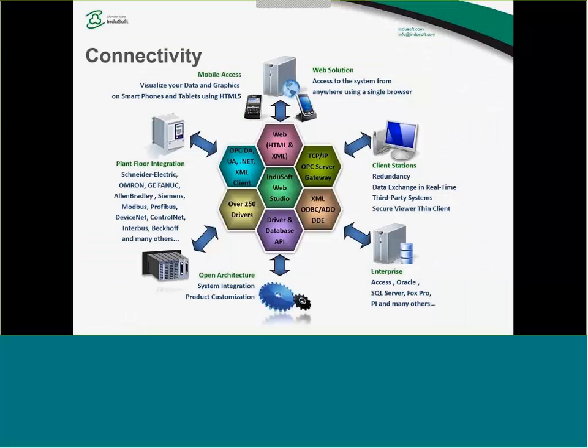Here we're talking a little bit about the connectivity that InduSoft offers. So basically, one HMI is supposed to have animations. It's supposed to show information about your field, to draw trend curves, to have an alarming system, and to animate graphics with information about your system. So all of that is going to be on the presentation level.